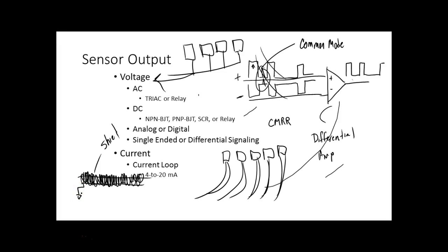So when we generate electricity, it's referenced to common. So your electromagnetic interference would come in here and hit your shield, and it would be shorted to ground. But a shielded cable costs a lot more than an unshielded cable. So that's why with Ethernet, we can buy shielded Ethernet cables, and I'll show you that too when we go over there.